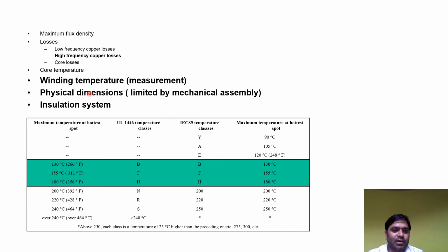The next important thing is the winding temperature after the core temperature. For winding temperature measurements, we need to put thermocouples on the winding, put the inductor into the actual application, and then do the measurement of the winding temperature. And for winding